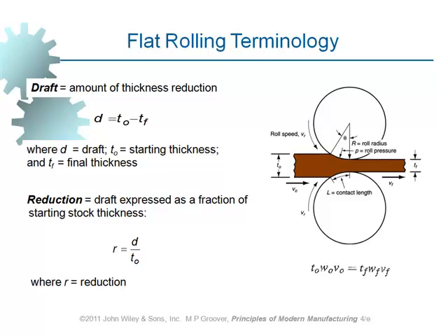Sometimes we produce a flat sheet, which is of common use, and sometimes we do produce different shapes, which I have got a number of shapes which can be produced by making use of the rolling process in the next slide. Well, as we can see here, we've got two opposing rolls which are used in the rolling process, and the material is actually pulled into the gap between the two rolls, and what is leaving the two rolls has got a smaller thickness. The initial thickness of the material is called T0 and the final thickness TF.